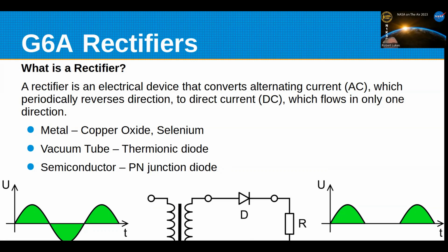Nicer if you have a bridge rectifier. Right. You can either go with a full wave, which would be 2 rectifiers and the center tap transformer, or a bridge rectifier, which is a ring of 4 diodes. And those come today packaged in a single unit with all 4 diodes in it. So it makes it very easy to do.